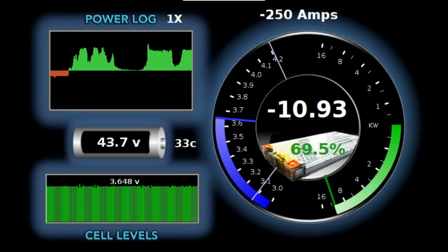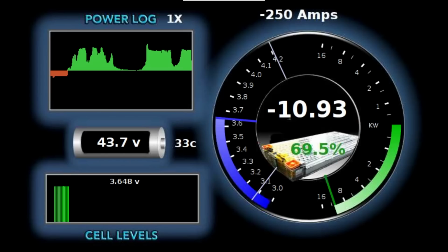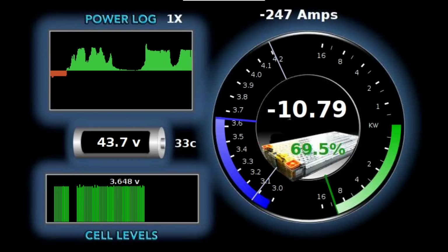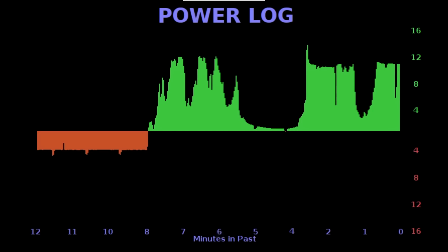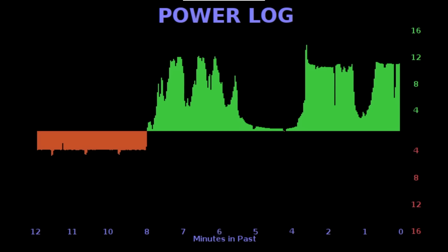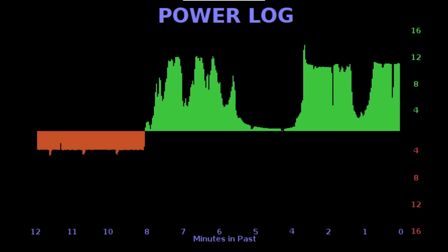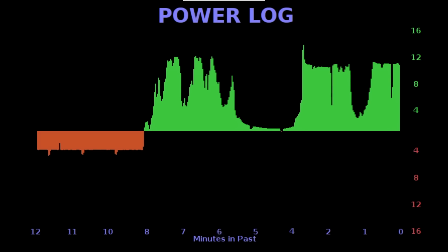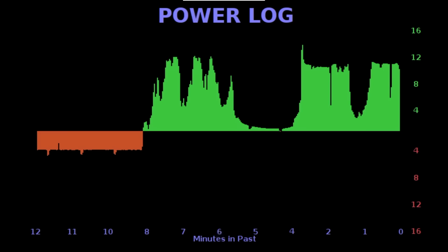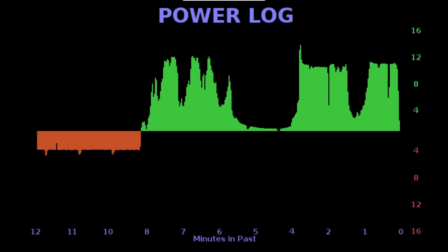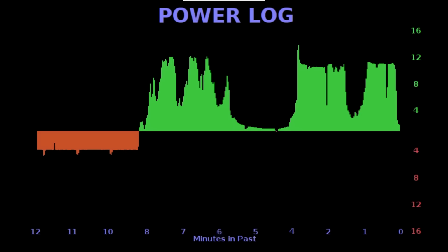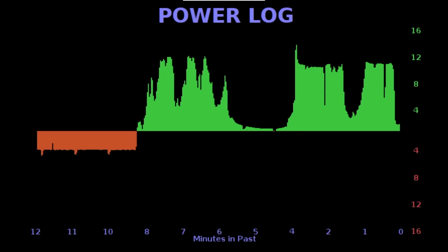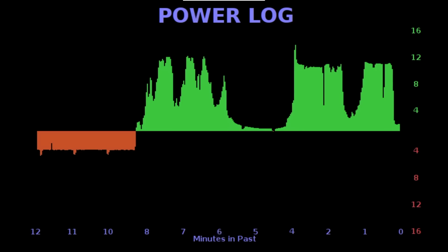The anomaly we just observed was that with very high rates of charging, at some point it will kick off, and I don't know how it did this. The solar edges lost confidence in the waveform from the inverter and kicked out, and they all went down simultaneously, and then they all started coming back up together 5 minutes later, which is their normal timeout period when you first turn them on.